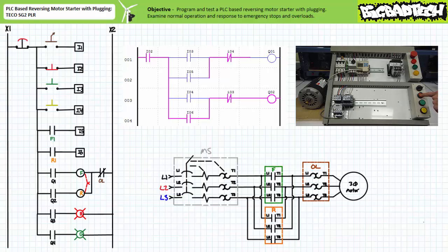When the stop button on input 2 is opened, the reversing contactor coil is de-energized, the reversing primary contact is open, and the motor turns off. You note the make instruction examining input I6, the R1 auxiliary contact, confirms the reversing contactor is opened and drops